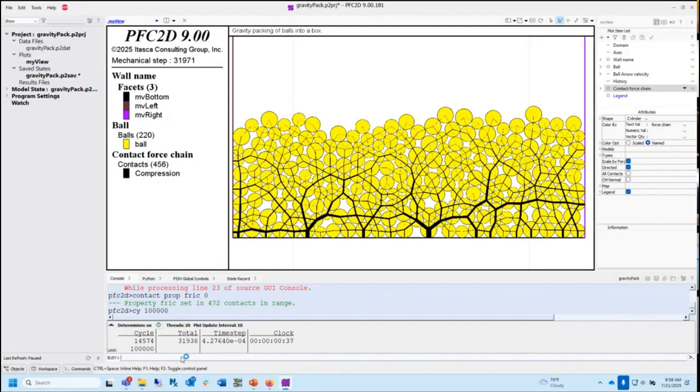You can think of it like if I had very high friction, high roughness, and I put them in a box, they would reach some state. But then if I remove the roughness, there's less ability to hold that shape. And so they're going to get closer together. Yes. If you want to get the most dense packing, you would want to have a zero friction coefficient. It turns out that it's the friction coefficient that's providing the strength of a granular material.